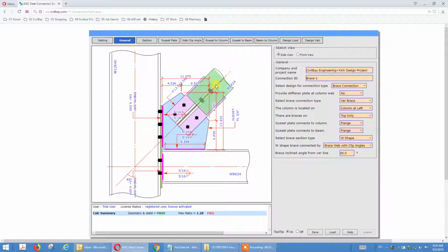And in that case, we want to take the strong axis radius, the larger radius of gyration. For strong axis, we have to connect a wide flange in this way. Okay, in this way, the out-of-plane r value is fully utilized. You have double unsupported length, but the radius of gyration r is also a large value, the strong axis value. Then we can get this brace member design to pass. Okay, we design this way.